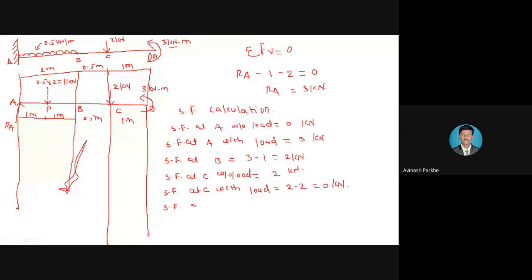SF at D. How many forces are present to the left side of the point D? 3. Three forces are present. One is the reaction, another is the UDL converted into the point load, and another is the 1 point load.